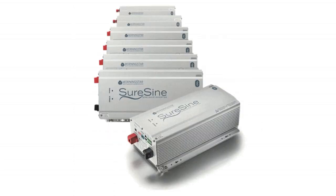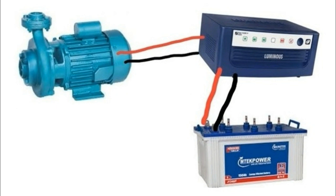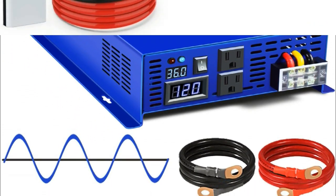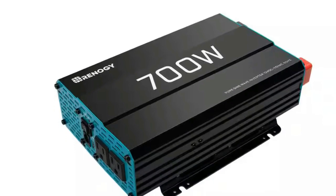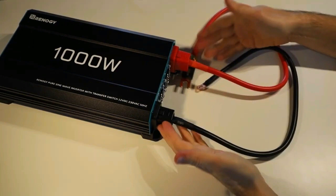Any device that has an inductive load, something with a motor, will always be less efficient running through an inverter than plugged straight into the mains electrical supply. It's all to do with power factors where the voltage and current become slightly out of phase. When choosing an inverter, always go for a slightly higher output watts than you think you need. It is better to have a 1000 watt inverter running at 700 watts than a 700 watt inverter running flat out. As a rule, assume your inverter is only 80% efficient and work from there.